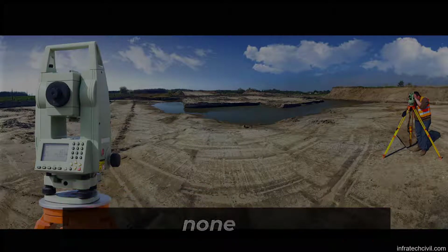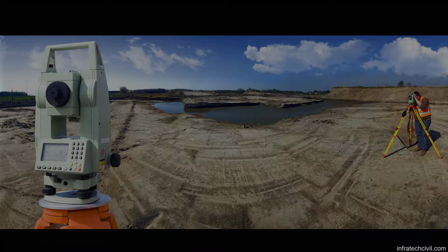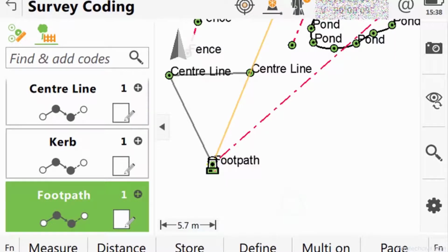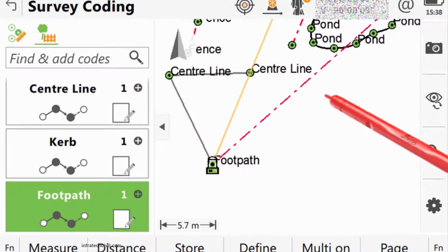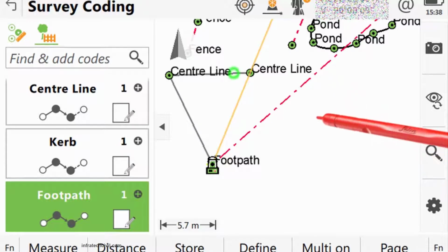The final feature to now look at is quite different from the AutoCode selection because we manually pick which line we want to measure to. In this case, instead of using the focus in the code boxes to define what line to measure, we'll actually tap on the line itself. We will press and hold on that line, and then use the menu that appears.